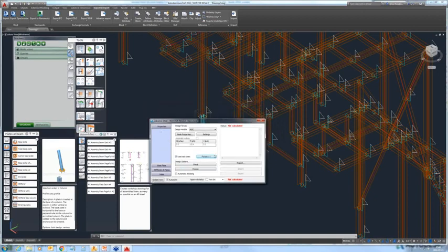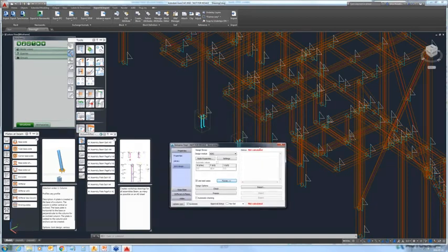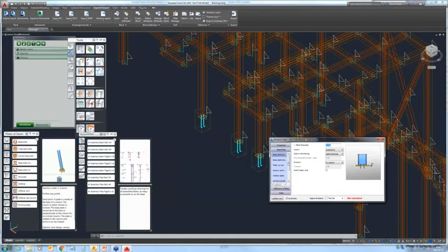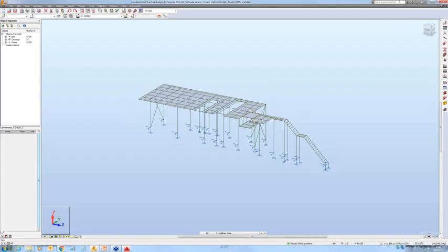And then in the joint design, you can see that you have access to the results from Robot. What is important is that when you have this group of connections, if you, for example, make a change to the master, all other slave connections follow. Okay, let me go back to the presentation.